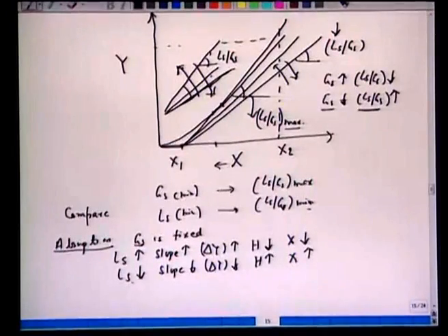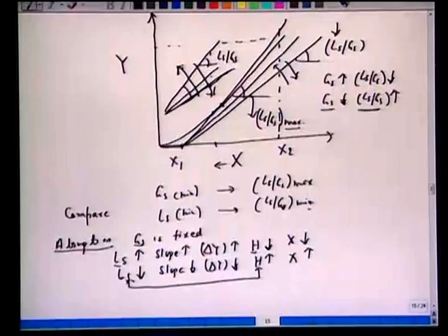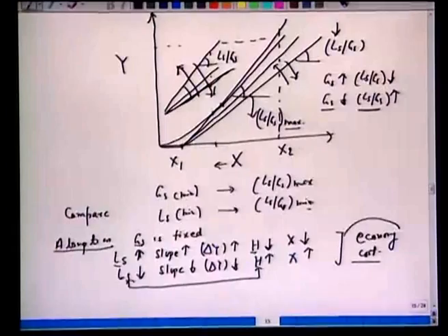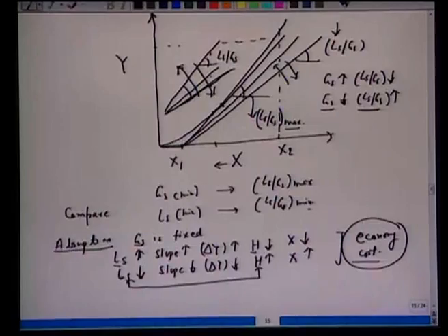So look at the economy here, LS and H. If the amount of LS decreases, height increases. If the amount of LS increases, that is the solvent requirement, then the height decreases. Of course, there is an economy here. There is a cost involved. Of course, we don't address economy and cost too much in this course. You will have an opportunity to address this aspect in the design course.